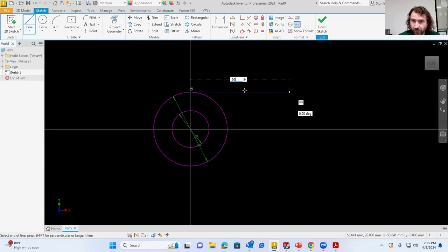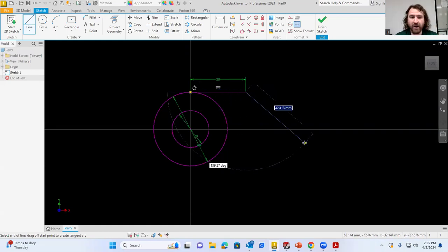It's going to be very hard for me to show it, but there it is right there. And then there's this symbol here. This symbol means that this line is tangent to this circle. That's a constraint. There's another video talking about constraints and sketches. And then this is the horizontal constraint. So this line is also horizontal. It's a horizontal line at 0 degrees. We'll hit enter, right? So there are those symbols again. And it's all the information about that line. It's very, very specific information.